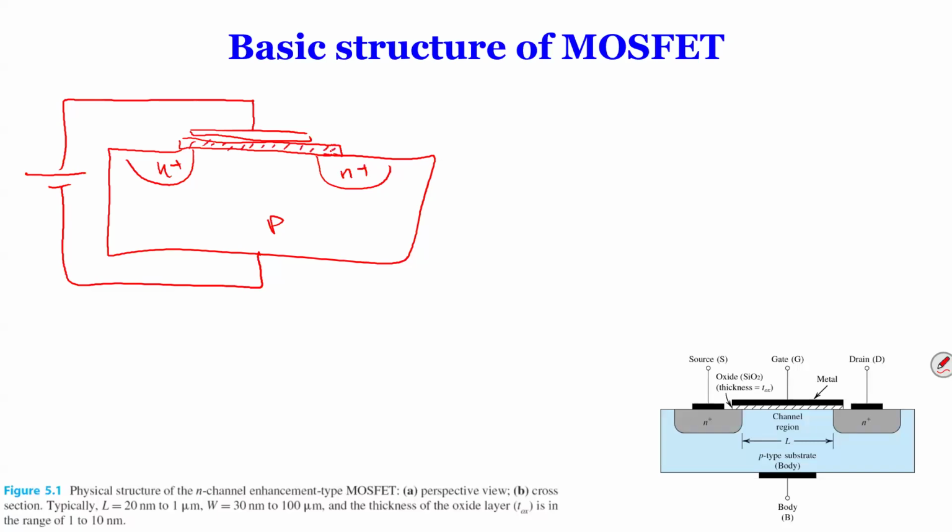All right. So what we're doing now is applying a voltage between gate and body. When you apply a voltage between gate and body, you see at the body there's a piece of metal as well. So between two metals, you apply voltage, what happens? No, there's an insulator, so there's no current. There's a voltage across these two metal plates. Well, what do you call them? It's like a capacitor, right?